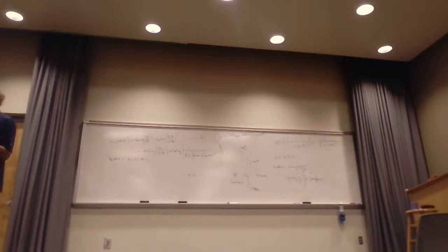You have cell phones, right? I haven't done this in a while, but you can go and actually see what the power level is that your phone's receiving from the nearest cell phone tower. And it will be not in dB microvolts, even though you can look at that signal strength, but it's usually in dBm. Do you remember dBm is power, right? And it would be the power the phone's receiving. It's not the power density.